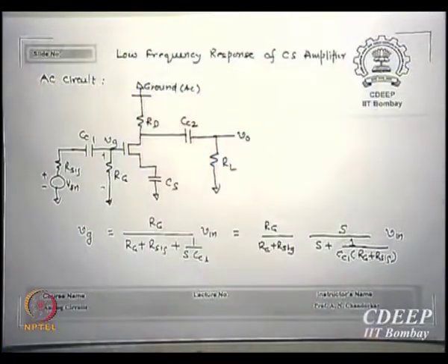Okay, let's do something different before we quit this amplifier frequency business. Last time we said that in all the analysis so far, the so-called coupling capacitors and the shunting capacitor across RS were neglected by us. We solved everything just for high frequency, and at high frequency they were all treated as short circuits.